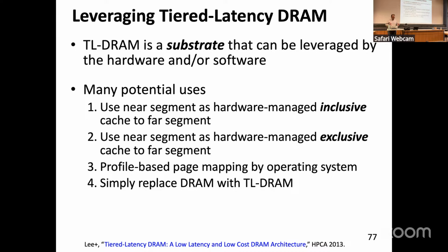And also you can rely on your luck, that you simply replace DRAM with TL-DRAM and hope that things are gonna work well. But it turns out that it doesn't work well. So you really need to intelligently manage and use this substrate. If you just naively replace DRAM with TL-DRAM, you're gonna actually lose performance, very likely.